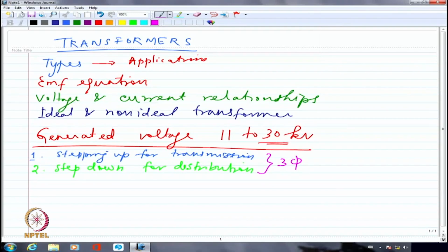No, newly there have been some conversions to AC. For example, if you look at the Western Railway route in Bombay, most of it is now converted into AC. Whereas, if you look at the Central Railway route in Bombay, that is mostly in DC. Okay? So, that is AC transmitted, converted into DC, and the DC motor is driving the vehicle. That's what I mean by DC. Basically, the drive train is DC drive train, basically.